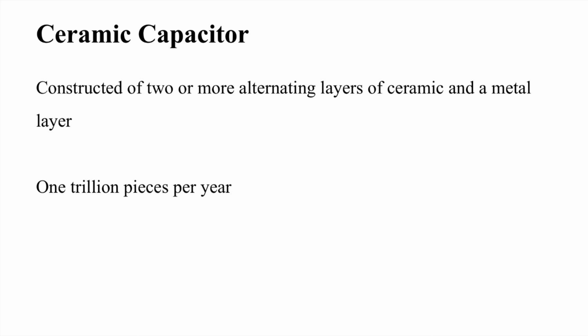A ceramic capacitor is a fixed value capacitor where the ceramic material acts as the dielectric. It is constructed of two or more alternate layers of ceramic and a metal layer acting as the electrode. The composition of the ceramic material defines the electrical behavior and therefore applications.